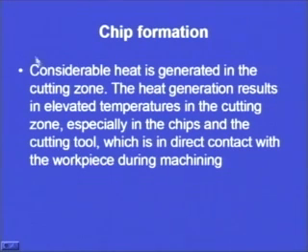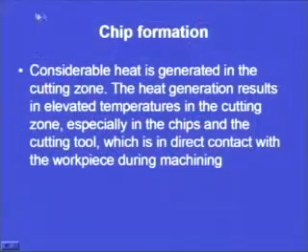Now another important point to note in case of chip formation is the considerable heat that is generated in the cutting zone. So, we have seen that forces and pressures are generated, there is distortion to the workpiece that may result, it may affect the surface finish of the workpiece, it may also result in excessive tool wear. Similarly, there is a large amount of heat that is generated. Now, considerable heat is generated in the cutting zone. The heat generation results in elevated temperatures.